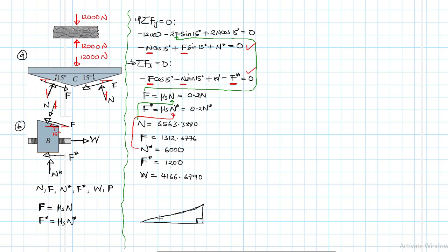It's a thread. So we have this angle there, which we are calling the lead angle, and then we have this one there, which is the L, and then we have this whole length, which is just 2 pi r. All right, and then we have L given as 7.5 millimeters.